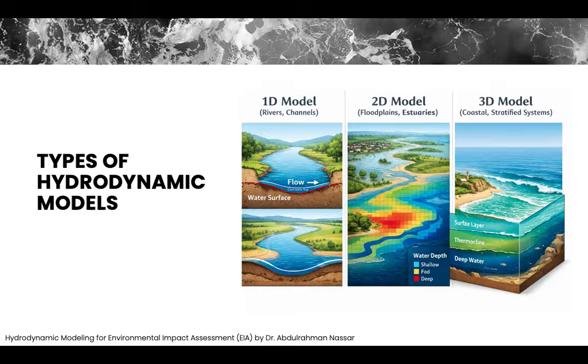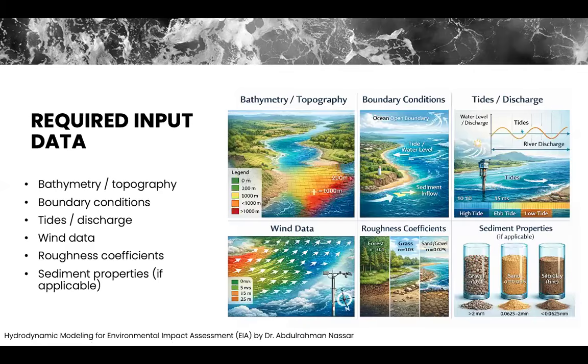But if we are talking about the sea surface, for example, the same power plant discharging directly on the sea surface, here a 2D model would be enough for this. A 3D model would also be perfect, but a 2D model will be enough. So we have different types of hydrodynamic modeling, depending on the purpose of the project.